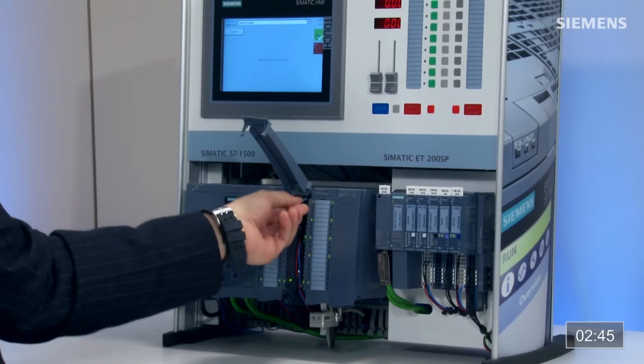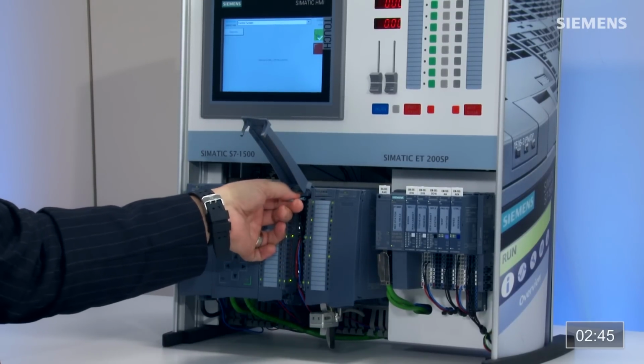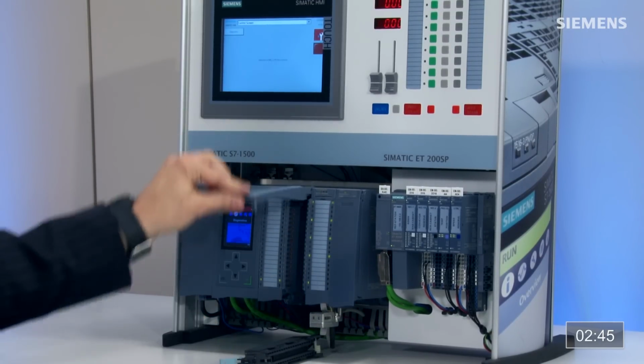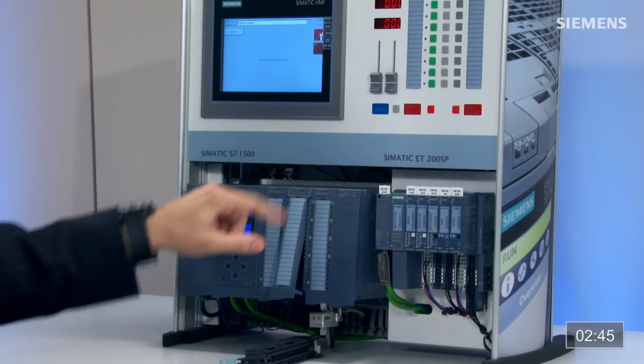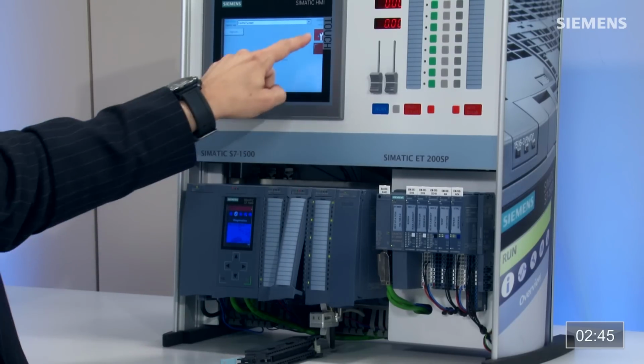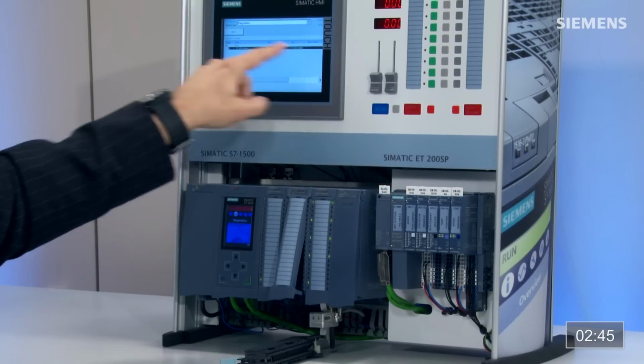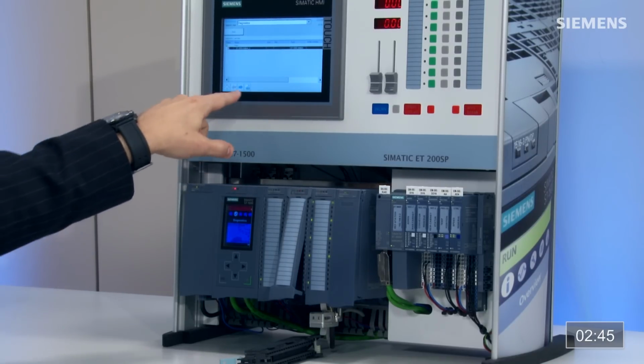And last but not least, wouldn't it be great if I could actually generate these messages up to the HMI on the machine, even in the stop mode? Well, we can. If I come over to this card right here, if you remember I did no supply voltage for this one, if I pull it out, you see the diagnostic indicator on the HMI has turned red and there's a wrench now. If I click on that, I'll see I have some kind of message in this actual local hardware architecture.